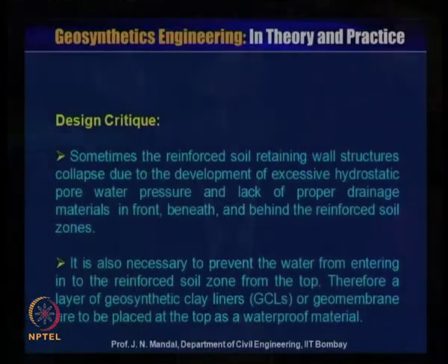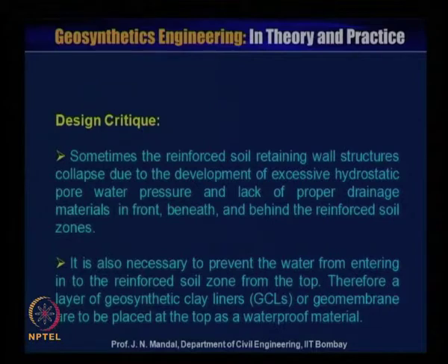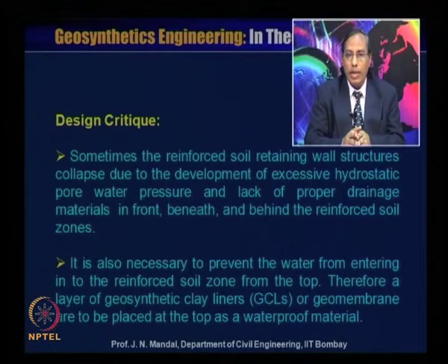Now, we will discuss some design critiques. Sometimes the reinforced soil retaining wall structure collapses due to development of excessive hydrostatic pore water pressure and lack of proper drainage material in front, beneath and behind the reinforced soil zone.